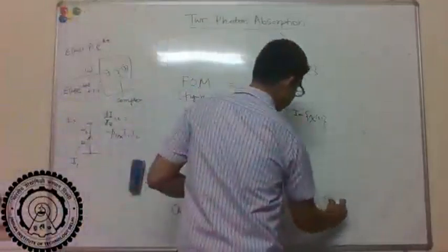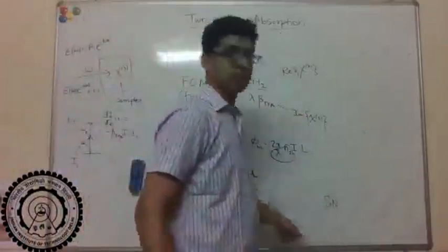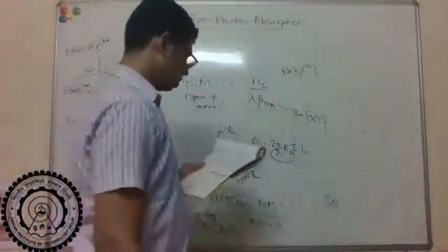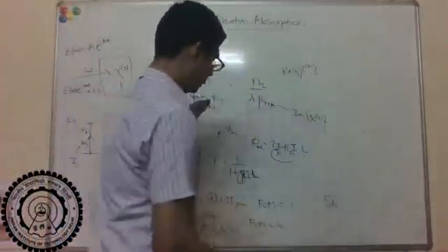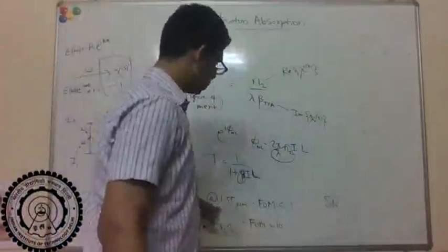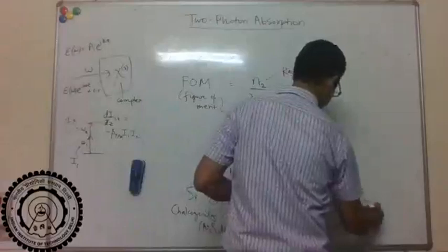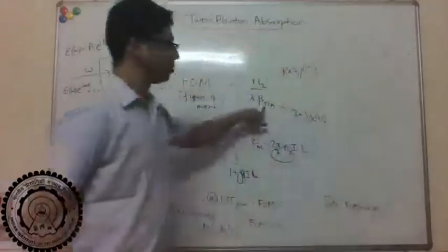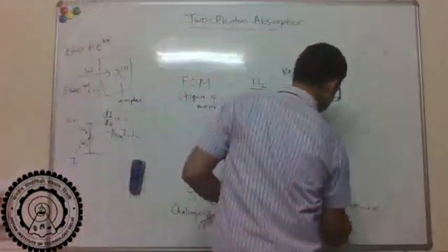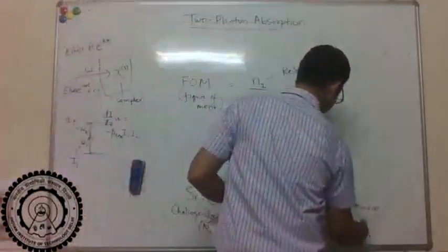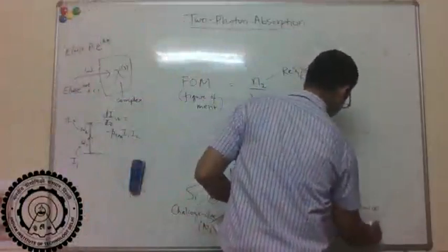Then another material used in micro and nano photonics, nonlinear photonics, is silicon nitride. For that, the band gap now becomes larger than twice this wavelength, so the figure of merit actually approaches infinity because beta is 0. Of course, N2 is only about 1/10 of silicon.